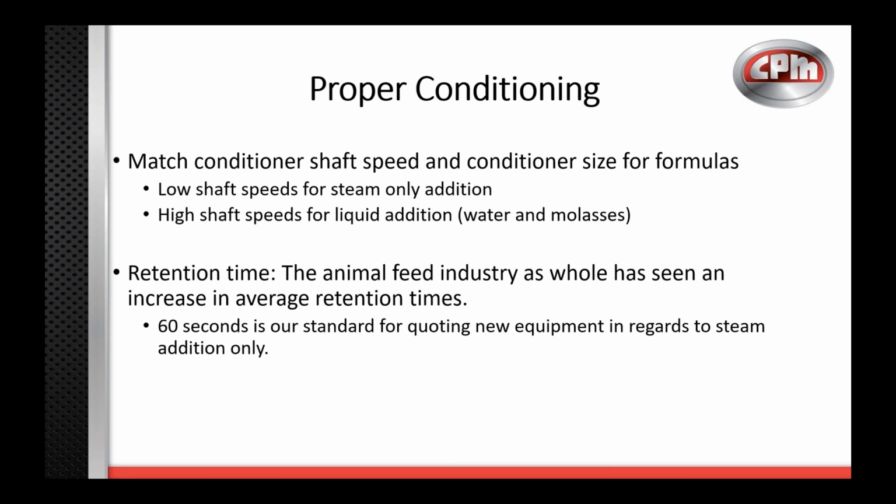And so overall, we've seen an average retention time for animal feed increase over the years. So now our standard when sizing a new conditioner is 60 seconds of retention time, and that's with regards to steam addition only. If you're using a high shaft speed, it's going to be a little different, that we might have to take into consideration.